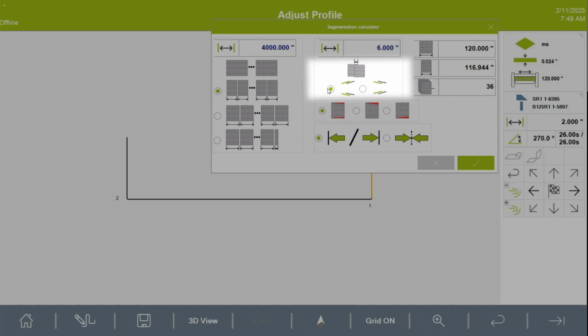All you got to do is tell it which way you want, because if you have a roof that's pitching down from right to left, this is the option you want to choose. If you have a line that's pitching and going from high ground on the left to low ground on the right, this is the way you want, because you want that water to flow according to your overlap or your underlap. Okay, then you got to manage the scrap.